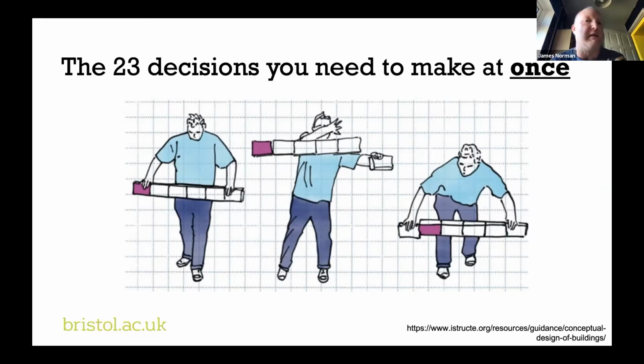And you know, that is because I'm a structural engineer. But if you're an architect, you may be making a decision about the grids of a project before you've even appointed a structural engineer, which is changing the structural engineer's ability to come up with the lowest carbon design solution. So decisions may have already been made. You may have implicitly made all sorts of decisions without ever knowing that you've done that.